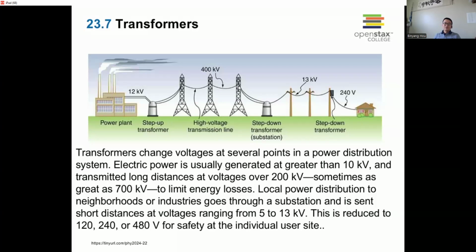In the high voltage power lines, the household voltage is not the higher one, right? It's pretty much 120 in the US or 240 in Europe. But by using high voltage, you can reduce the loss of power through the lines, because higher voltage means you have less current in the wires, and the lines have a fixed resistance that's not changing so much.